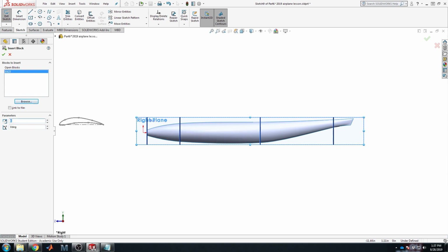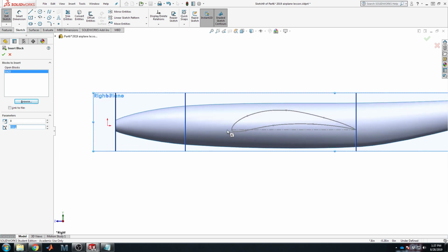Like if you were going to be using a large chord airfoil and you had very, very high camber, the reason I backed away from the root chord of 8 inches here is that look how much of the fuselage height that occupies. You would be able to do a blend if you had to, but that blend is now going to start creeping into very angled portions of the fuselage. You'll be getting into something, attachments at 45 degrees, etc. So could it work? Yeah, probably. Especially with airfoils as high, you really do probably end up with some root incidence.